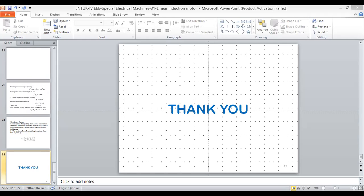Next, these resistances may be divided into two categories. The first is the secondary copper loss, and the other is the output of the motor. Here, the motor output is represented by a fictitious resistance, which is equal to R2 times (1 minus S) by S. This is the equation. To this circuit, the secondary leakage reactance X2 is added.